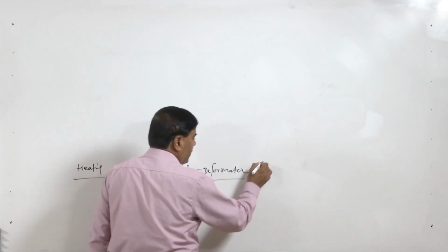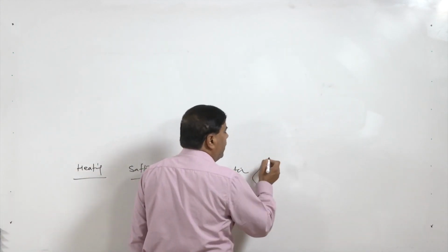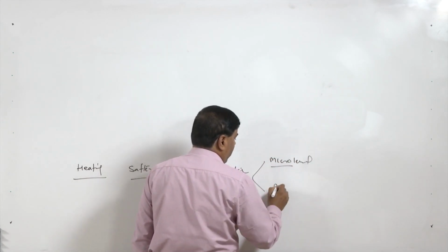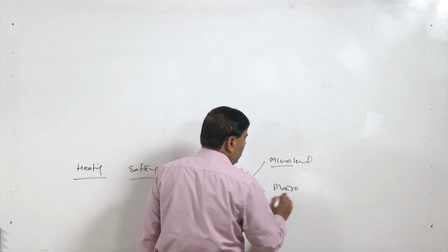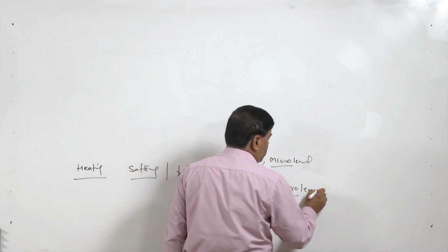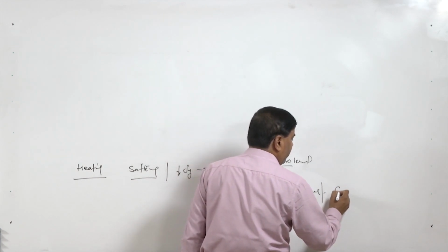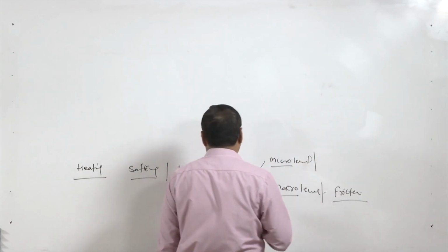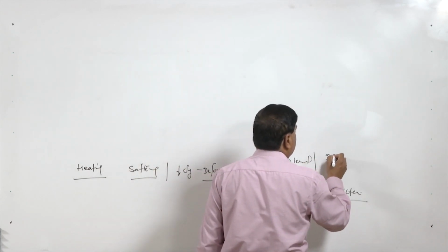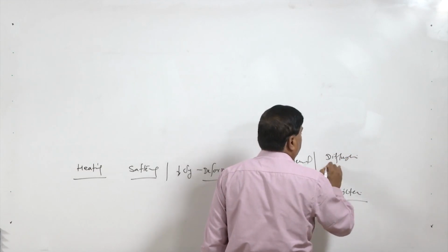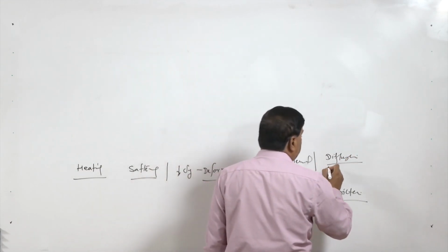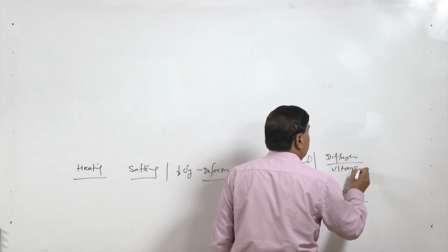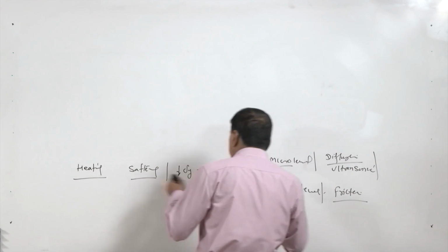Sometimes this deformation can be at two scales. One is just at the micro level and another is at the macro level. Sometimes the deformation is large, at the macro level. This kind of thing is observed in, say, friction welding or friction stir welding, and micro level deformation occurs in, say, diffusion welding when high pressure is used, or in ultrasonic welding, where very little pressure is used. So, there are different levels.